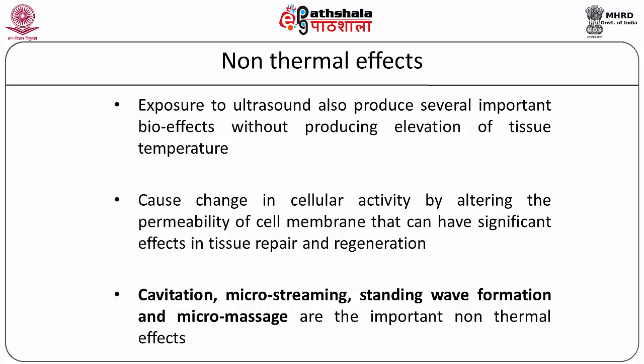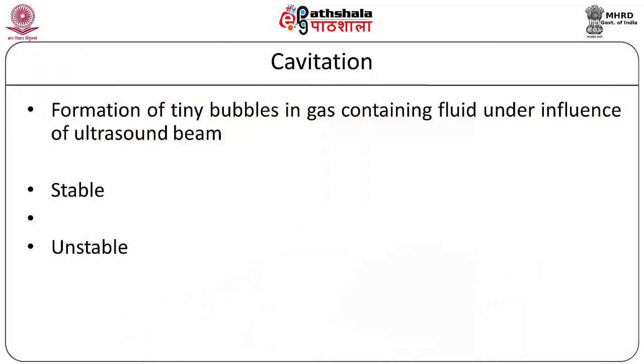Cavitation, microstreaming, standing wave formation and micromassage are the important non-thermal effects of ultrasound, which are produced due to high frequency pressure oscillations associated with the exposure to ultrasound. Cavitation is the formation of tiny bubbles in a gas containing fluid under influence of a mechanical wave. There are two types of cavitation: stable cavitation and unstable cavitation, which is also known as transient cavitation.